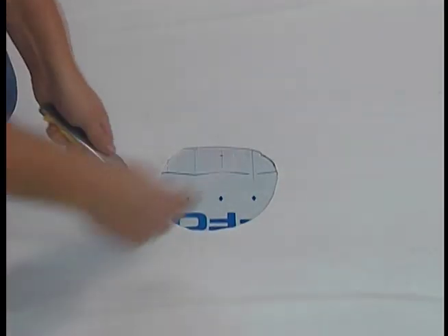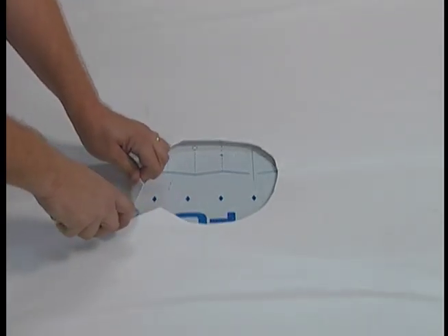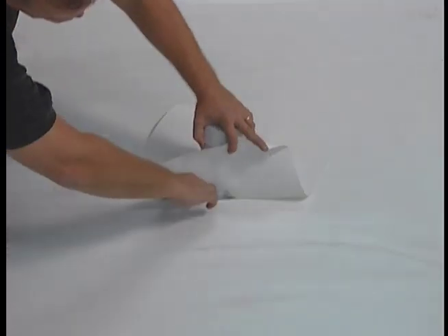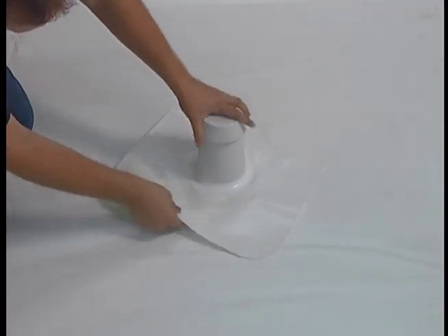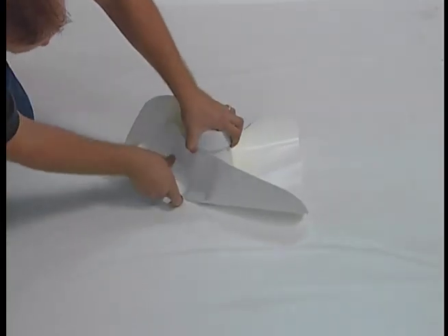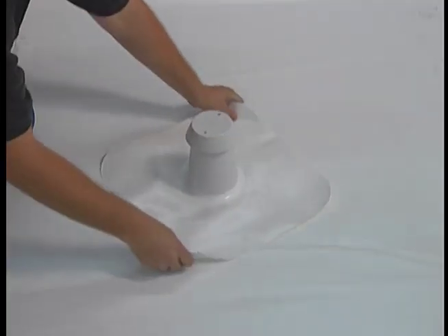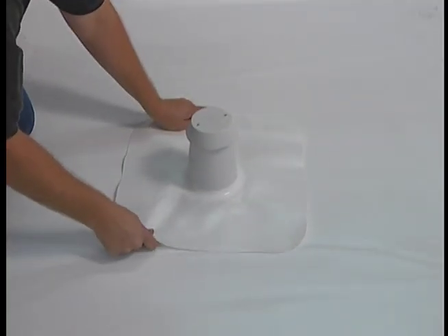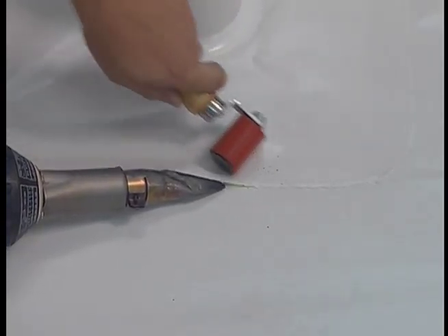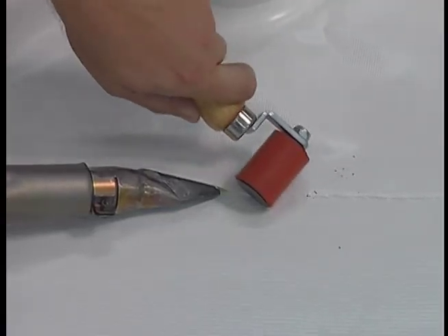Make a single 2-inch cut from the edge of the hole. This will allow you to insert the vent feet under the membrane. Place the vent over the hole and slide 2 of its feet under the roof membrane. Rotate the vent until the 3rd foot comes to the 2-inch cut. Continue to rotate the vent and guide the 3rd foot through the cut, placing all 3 feet under the roof membrane. Then, using a heat welder, field weld the prefabricated vent skirt to the deck membrane.